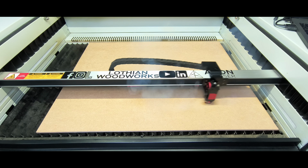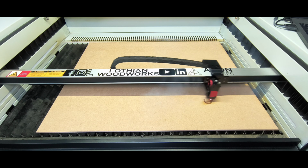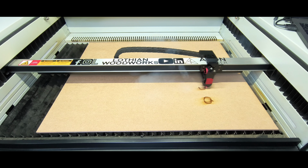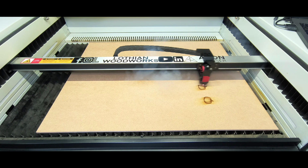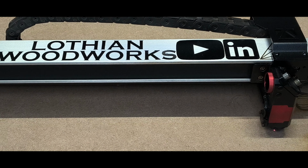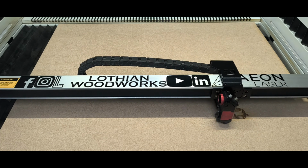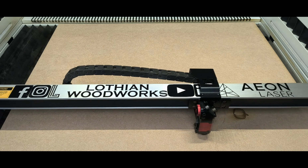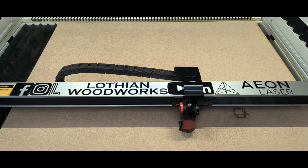So as you saw me in LightBurn, I was just reorganising the cut files to make sure it engraved first. That's what I'm doing just now. And once it's done that, it'll start doing the kiss cut, which, again, you can barely see on camera. I'll zoom in, and you can see it's barely scoring the very surface of the board there, just to make sure everything's lined up perfectly.